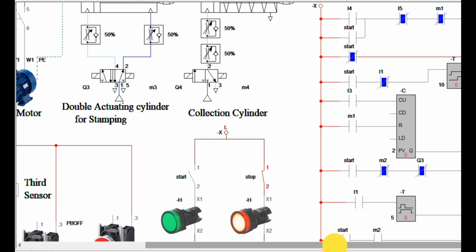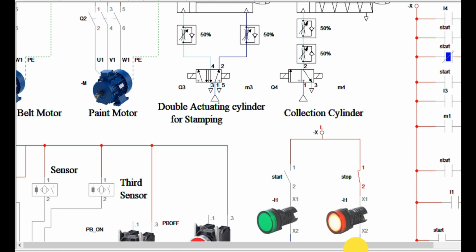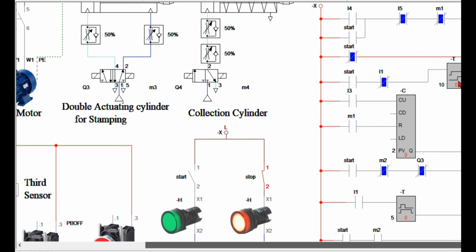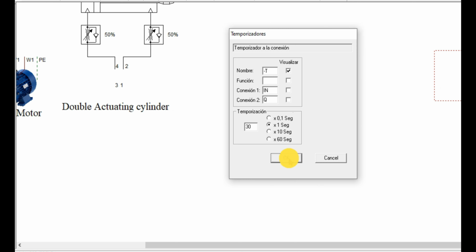Okay, the process has been stopped, the motor is also turned off, and this contactor is opened. Now I am adjusting it to a higher value so that we can see other processes. Firstly, stop it and adjust it to 30 seconds so that we can get other scenarios.